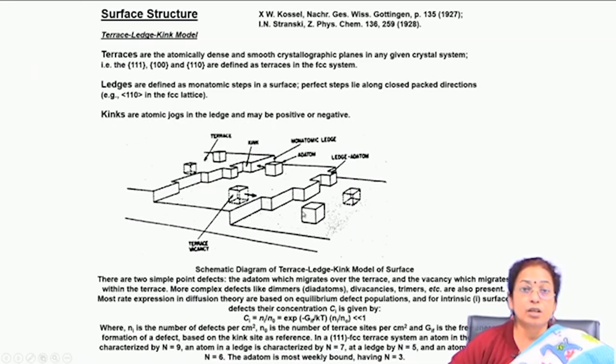of the materials. So, you will find that it is very easy to create vacancies, and as a result, if you talk about the phenomenon of diffusion, you will find that diffusivity along the surface is much higher than that of grain boundaries and that of the bulk of the materials, because it is easy to migrate atoms on the surface, and it is easy to generate defects on the surface, particularly point defects where an atom can sit and then get diffused in.